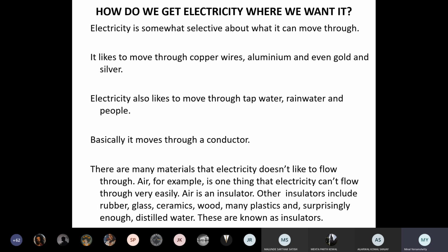You need to be very, very careful. The reason for writing this separately was to make you aware of it. That's the reason, when we do fire safety and firefighting in the next semester, this is the point you need to remember. All your MEP rooms, MEP is mechanical, electrical, plumbing rooms, will not have a water-based firefighting facility. So you will not have sprinklers there, you will not have wet risers going inside, no way, because that is double trouble. If you don't die by fire, you will definitely die by electricity. So these are the problems that you need to understand.